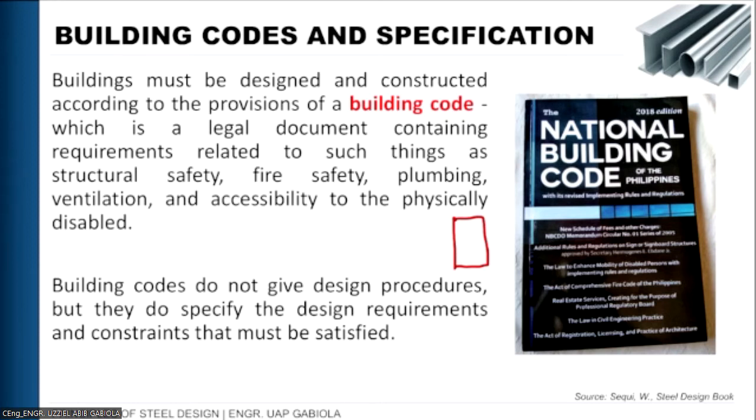There is a section in the building code that when you try to attach your structure on one side, you should install a firewall before you construct your structure. You also have different requirements for the offset on the front, at the end, and at the side. All of these are indicated here in the National Building Code because it promotes safety. The firewall is for fire safety so that the adjacent building will not be affected when a fire happens. And then other requirements, like what I said earlier, the minimum clearances, are written in the National Building Code.